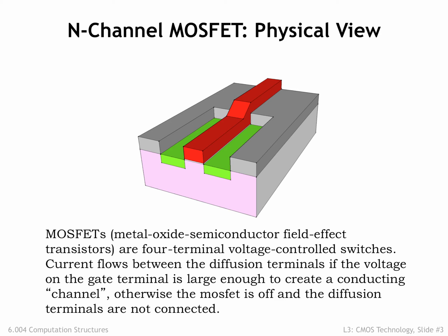For many years, engineers have been able to shrink the device dimensions by a factor of 2 every 24 months or so, an observation known as Moore's Law, after Gordon Moore, one of the founders of Intel, who first remarked on this trend in 1965. Each 50% shrink in dimensions enables integrated circuit manufacturers to build 4 times as many devices in the same area as before, and, as we'll see, the devices themselves get faster too.